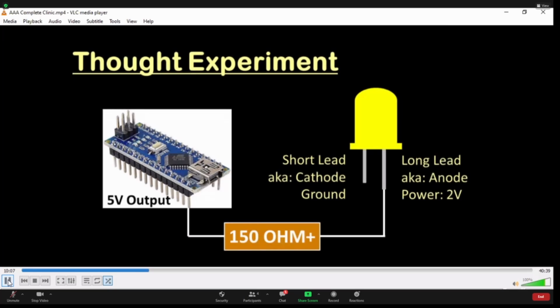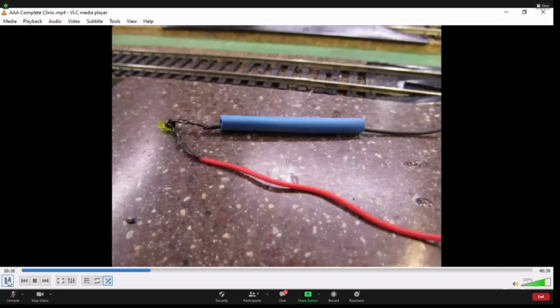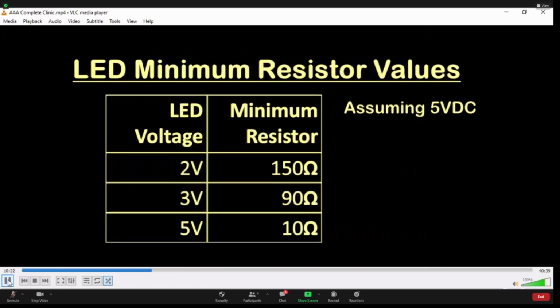Although I can add the resistor to either wire, I am going to splice it into the black wire, about 2 inches from the free end. After soldering, I'll insulate it with heat shrink wrap. Different LEDs need different size resistors. If you use too small of a resistor, the LED will blow. Too large of a resistor and the LED will get dimmer.